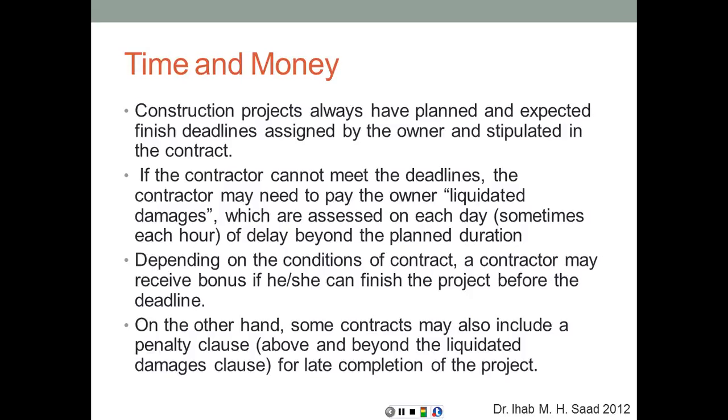As you may have learned in contracts and specs, liquidated damages are not a penalty. They are not considered a penalty, but they are damages that the owner would suffer from the late completion of the project. That's what the contractor would have to pay back. On the other hand, the owner may impose another penalty clause in the contract, which is usually counterbalanced by a bonus clause as well. So most likely, if the contract has a penalty clause, it's going to have also a bonus clause for finishing earlier than scheduled.